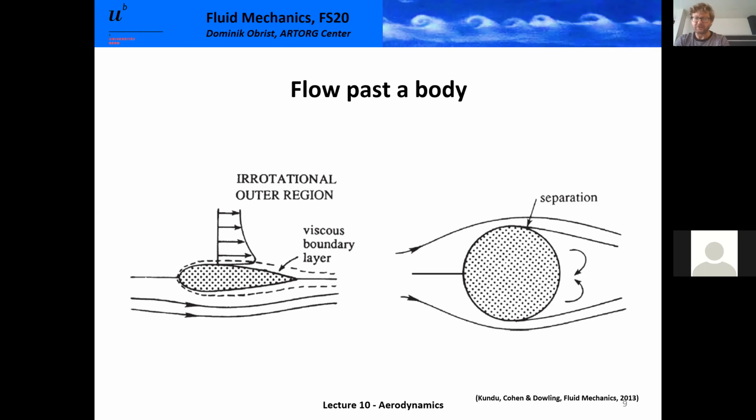In many cases, not always, but in many cases, it is a turbulent wake. It's a wake with turbulent flow in it. The flow conditions in this wake are very much different from what we had if the boundary layers were to remain attached all the way to the trailing edge of the sphere.